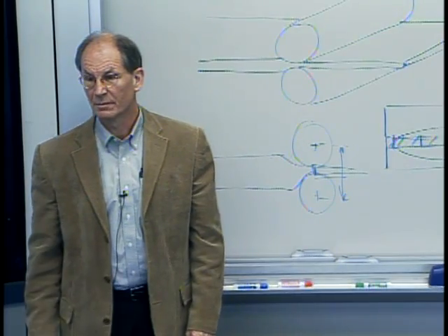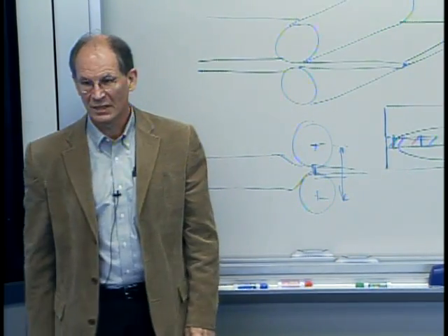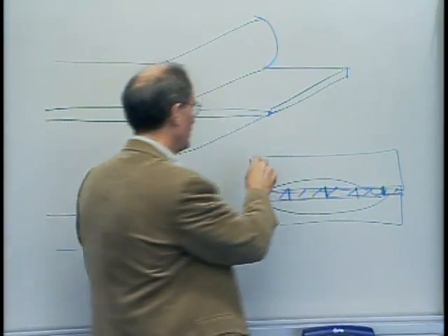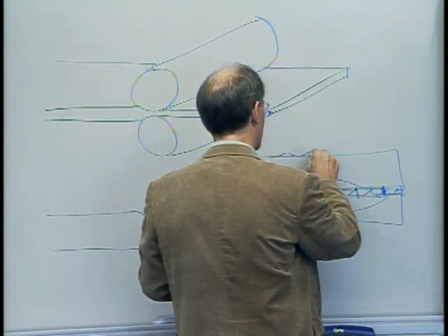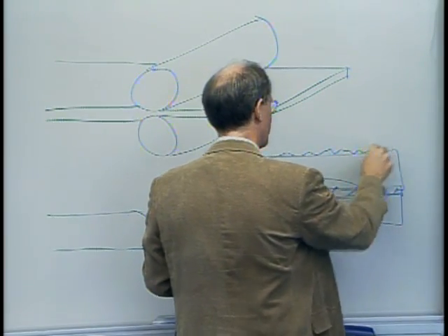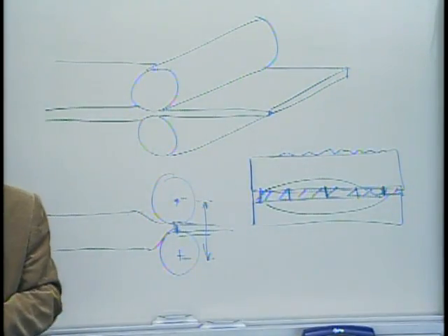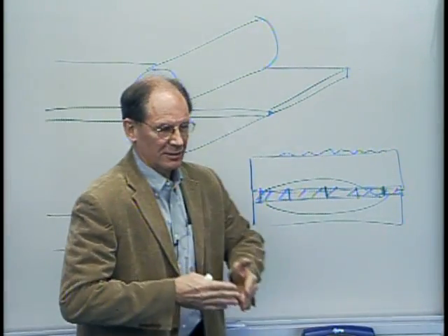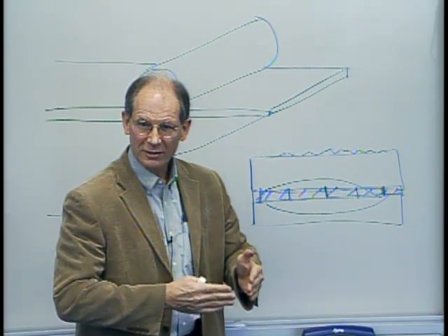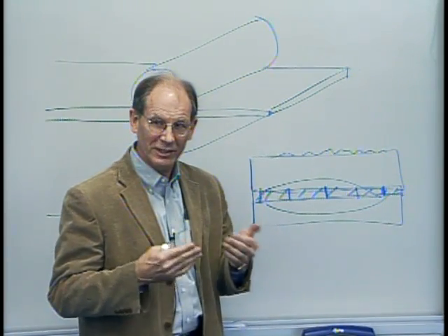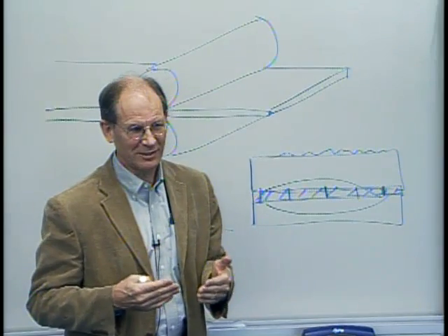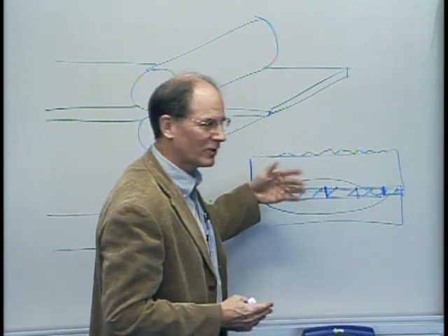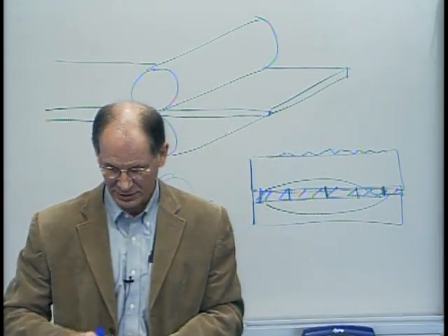Would you like locally heated through heat? Yeah, in fact, that's what is done to get small displacements, to be able to put some different profiles on that. You'll locally heat it or cool it in response to feedback to actually slowly move the tool locally, a little bit fatter here, a little bit less there. You can imagine if you only need 10 microns, something like that, it doesn't take a lot of heat. And yes, indeed, you're going to say, oh, well, how localized can that be? And that's the trade secret they won't tell anybody about.